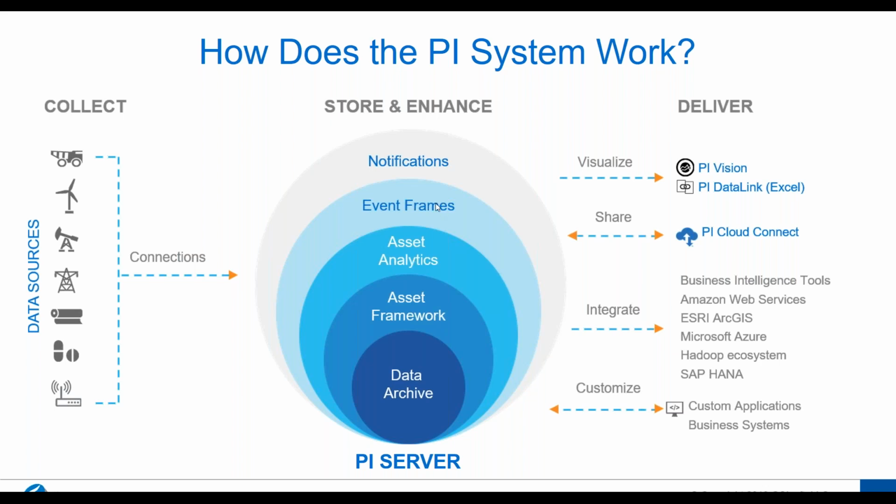There's a specific type of analysis called an event frame that takes place on a specific piece of equipment, and it has a user configurable start event and a user configurable end event. It could be the same condition, or it could be two different conditions. When that event happens, the user can configure what pieces of information they want to get.